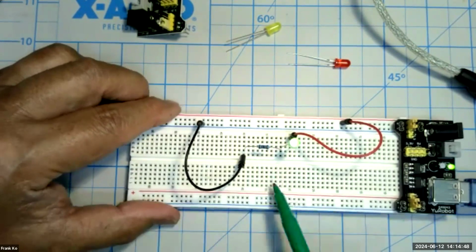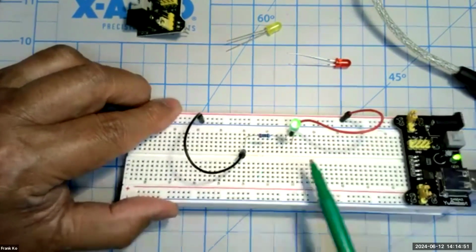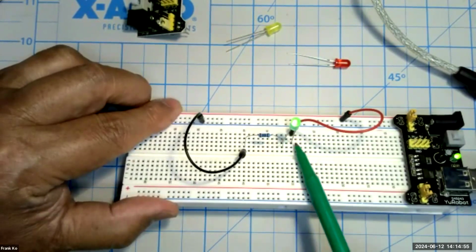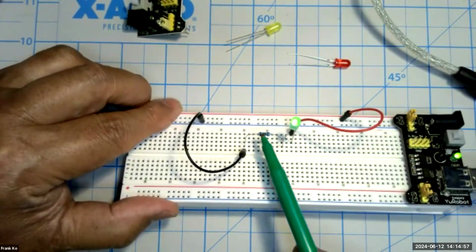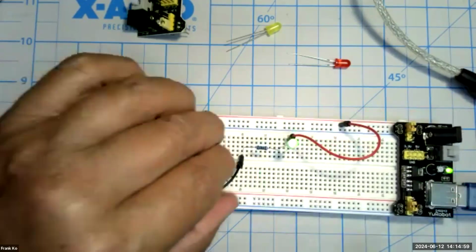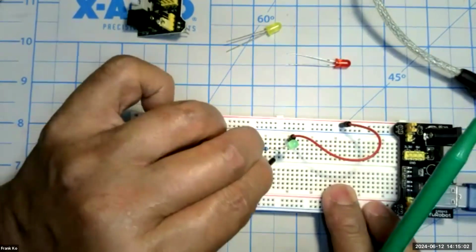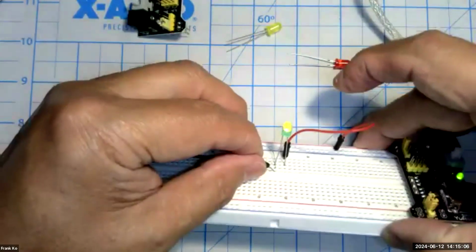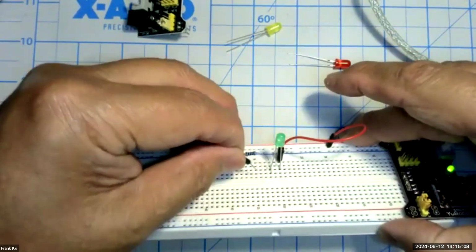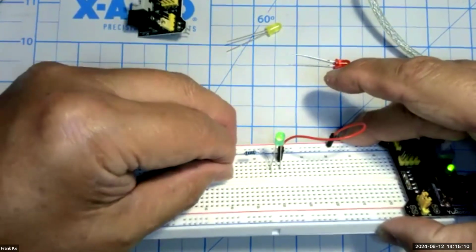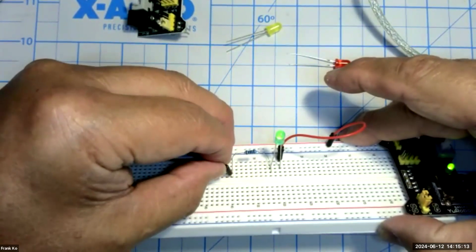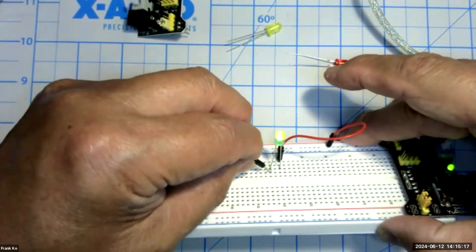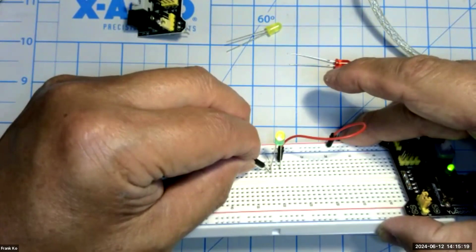One resistor, in addition to an LED set up this way, is for the purposes of protecting that LED so it doesn't burn out because of excessive electricity. Without the resistor, if I go to connect this, ooh, it's quite a bit brighter. You might not notice it straight on, but that's quite a bit brighter. And if I do this here with the resistor, it's not as bright. So this is with the resistor, and this is without the resistor. I'm bypassing the resistor, and you can see it's quite a bit brighter.